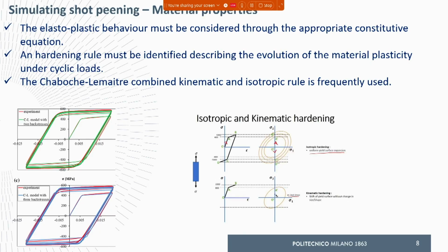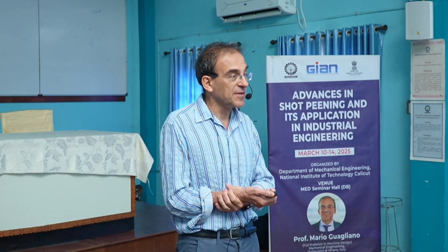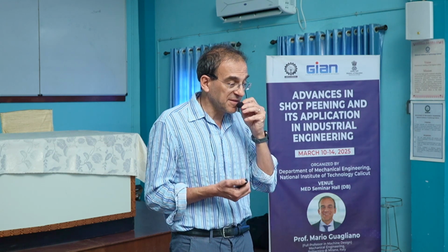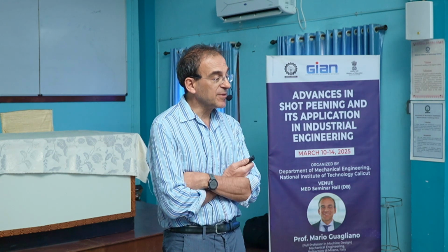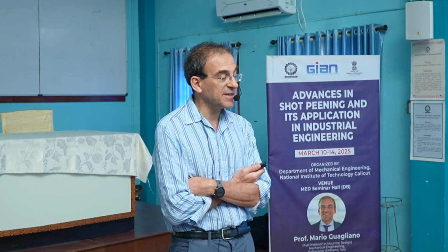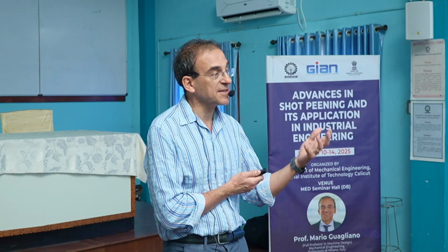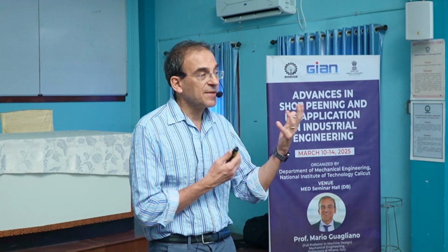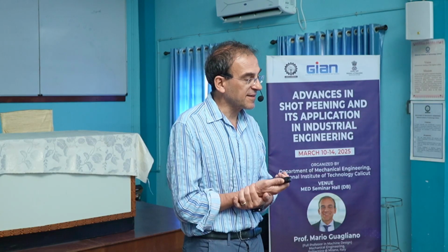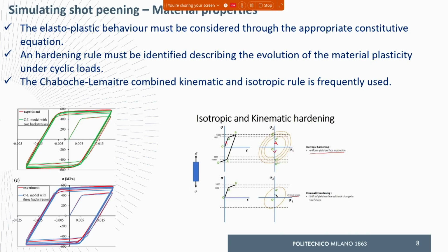Okay, and also, since we are in a condition where cyclic elastoplastic behavior is happening, we need a hardening rule that defines how the elastoplastic behavior of the material changes with the number of cycles. That is to say, a hardening rule. The most widely used hardening rules are the so-called isotropic and kinematic hardening rules.